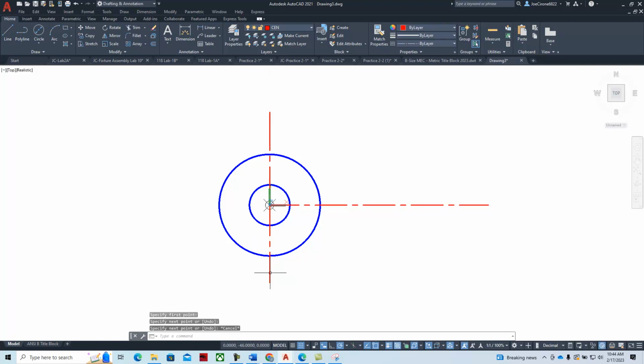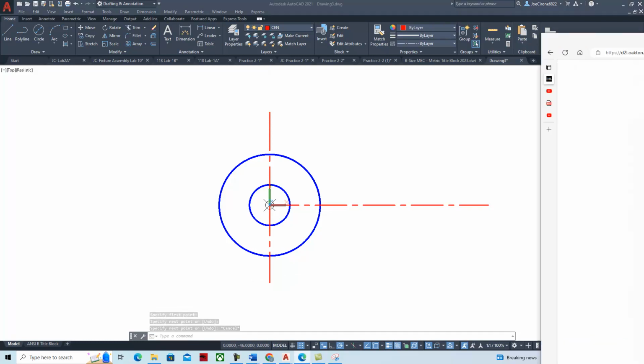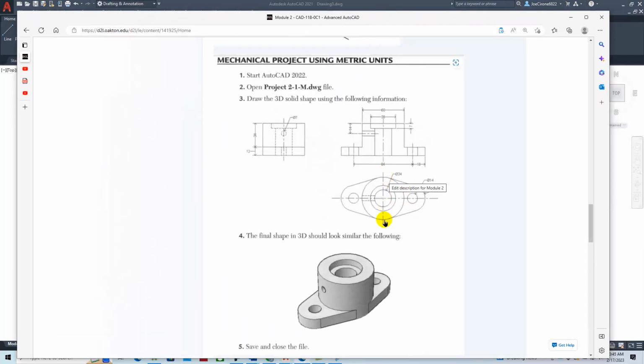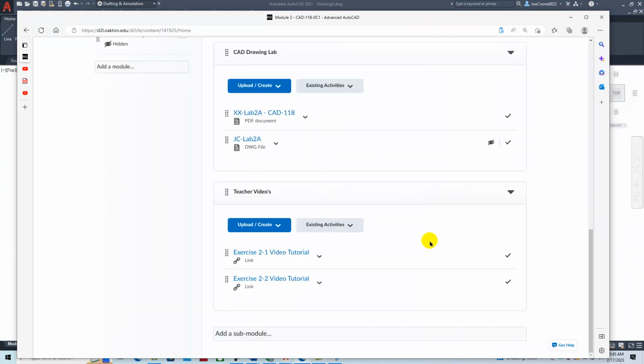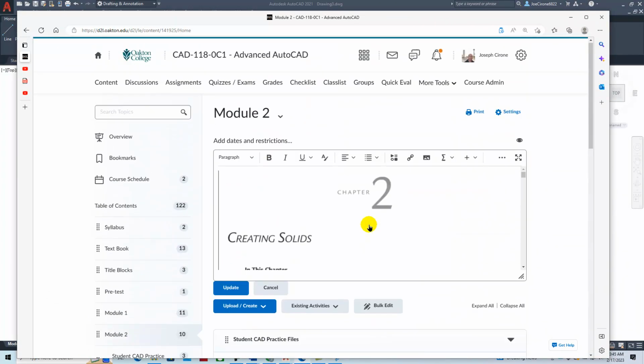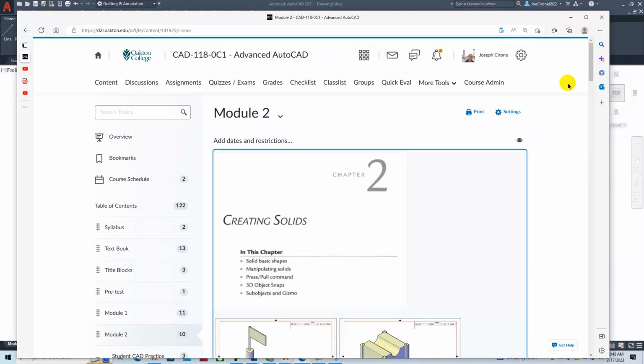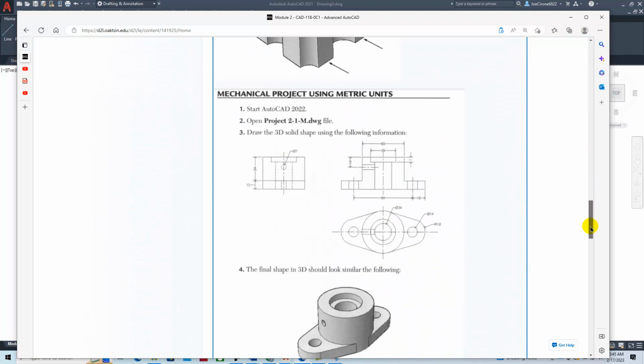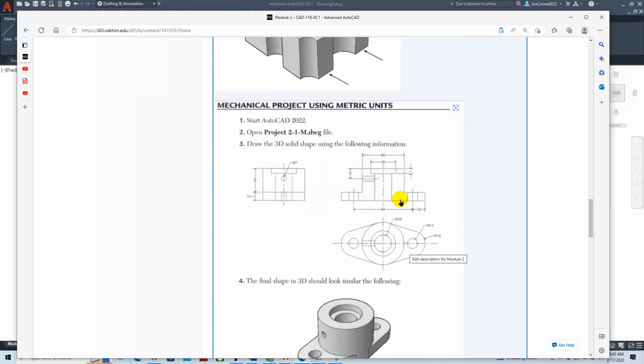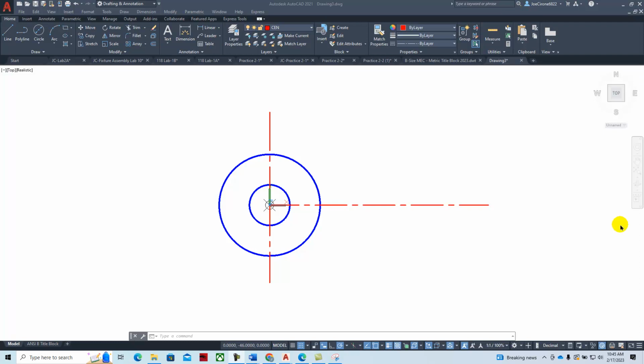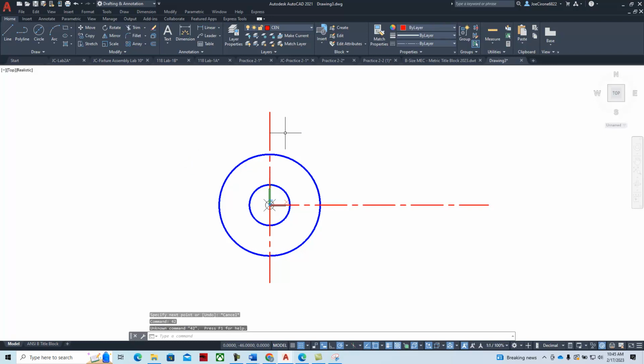And then we'll offset that line. This one right here, to locate this circle right here. Sorry about that. For this circle right here. And so that's located, if we take 84 divided by 2, that'll be 42. So we'll offset 42. Try that again.